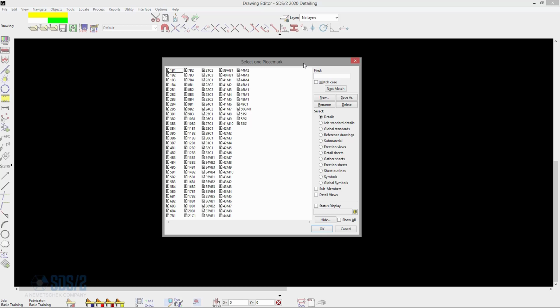If we're keeping the same auto-loading options, but we want to change something as far as the order of things on the sheets, or we need to reorder them, then we are going to have to run the auto-loading once to change the piece marks all to something else, and then delete the sheets a second time and reload them at the new piece mark. So let's take a look at some options for that.